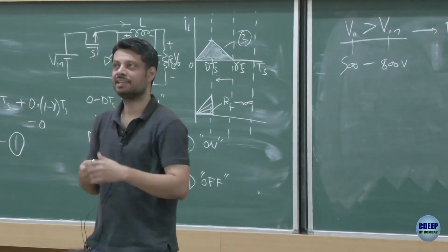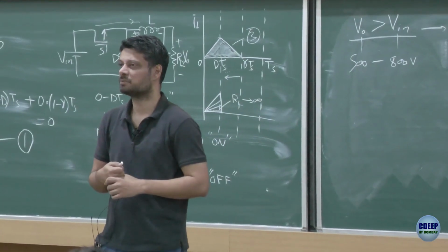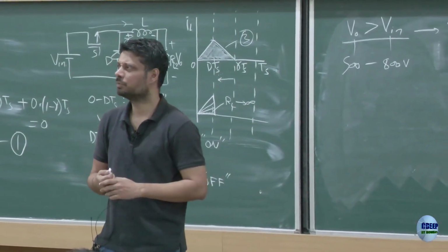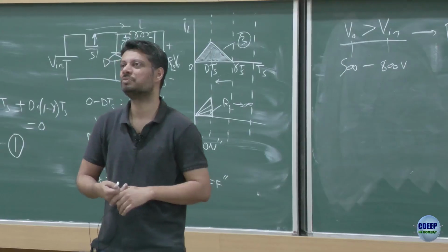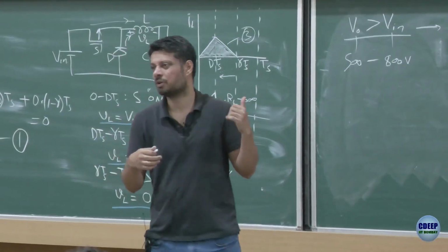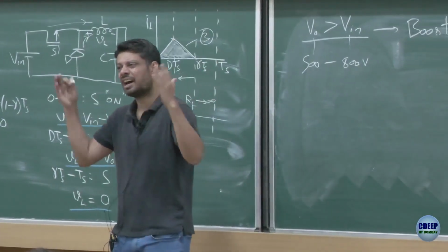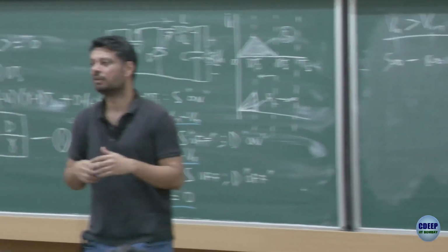Yeah, so what he's saying is, you're talking about high voltage DC transmission. You don't usually use boost there because there you want to increase it to a very, very large amount. We'll see later on, boost is not really capable of doing a very large boost.